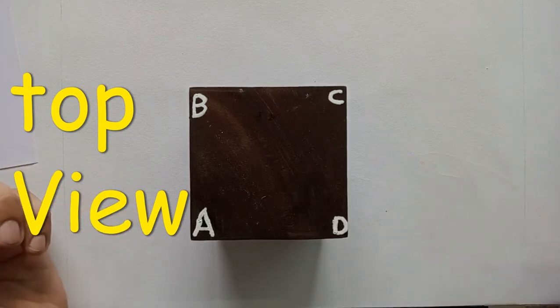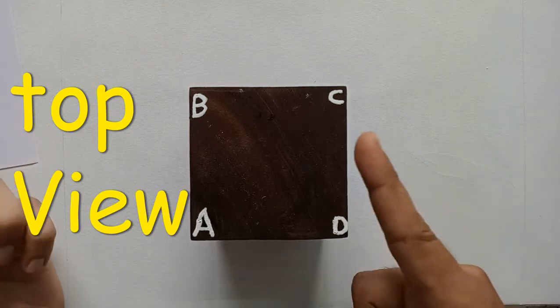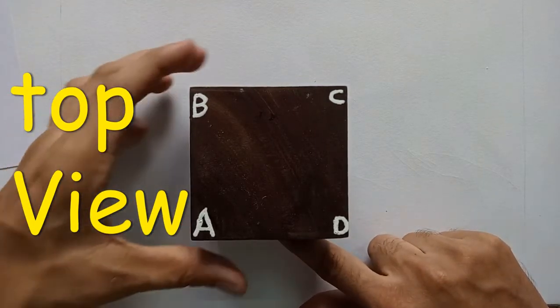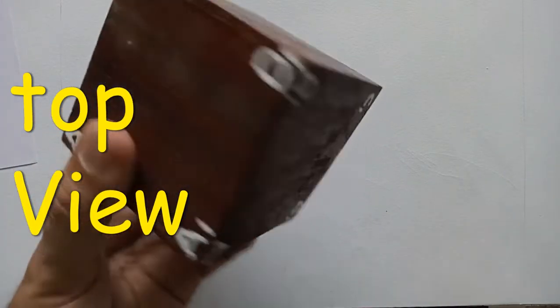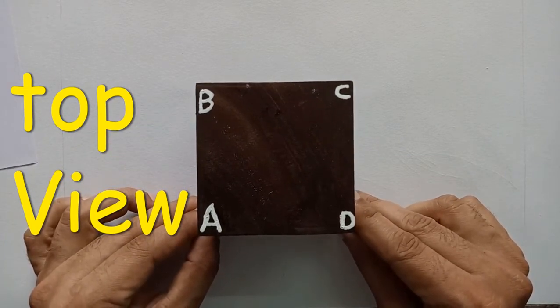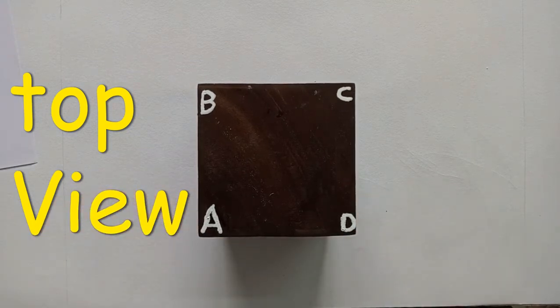And also the other square faces are invisible in the top view. Here we are having a square face, here also we are having a square face, here also, and here also, and it is resting on a square face also. That particular square face is also invisible when you are observing it from the top. So please remember this. This is how it is placed on the horizontal plane. When you are watching from the top, you are getting the top view as a square, and you are getting it in its true dimension.